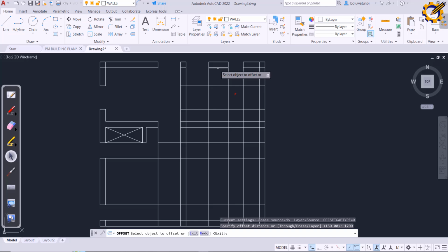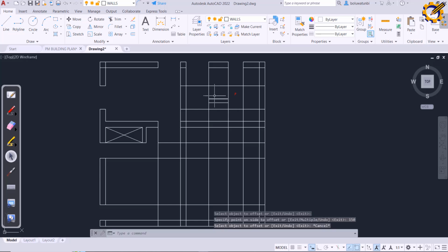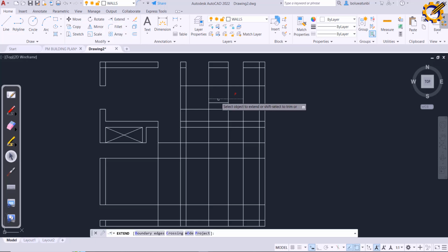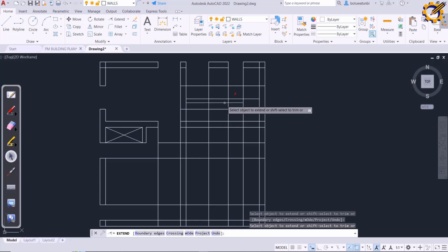Okay, I shouldn't have framed that in. Okay, no voila. So see what I'm going to do now. From here, I offset 1 2. Yeah. So then I offset 150, 150 beside it. But I need it to run across. So for it to run across, I just use my what? Extend. With extend, I can extend this, you see, and this, to keep extending the line until it reaches where I want it to reach. And I think it is okay like this.